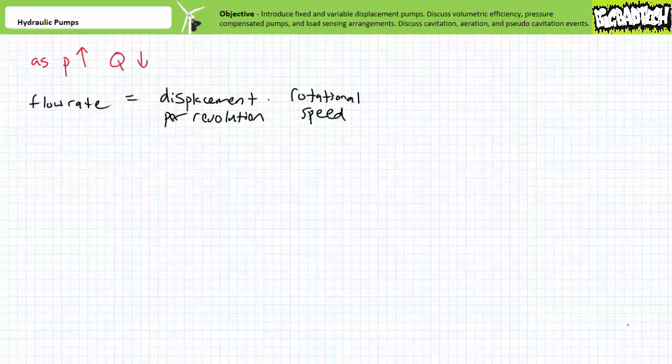In a perfect world, an ideal pump could produce a constant flow rate at whatever pressure required, but this is not the case. As pressure increases, flow rate ordinarily decreases due to increased leakage, friction, and, at risk of blowing your mind, the tendency of the prime mover to rotate slower at higher torque requirements characteristic of higher pressures.